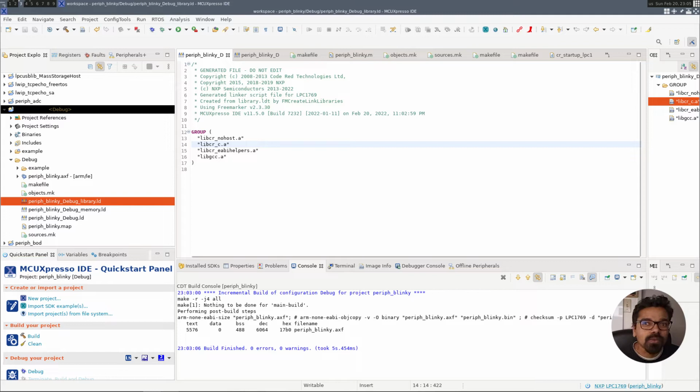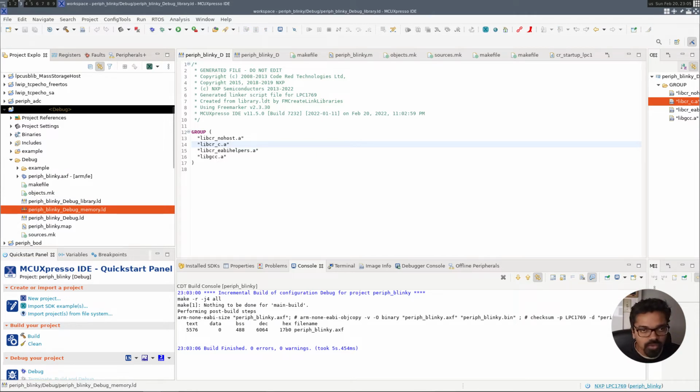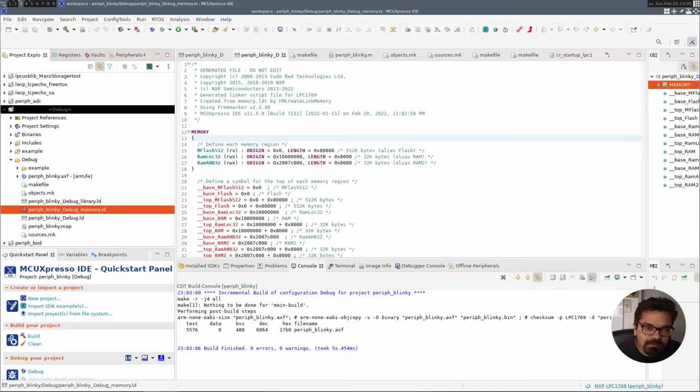But why is there an extra step over here? The reason we have this extra step, no matter what the chip is or who the manufacturer is, is because you need to compile your code based on a very specific target. That's number one. But two, that target might have a different memory layout, and different pin configurations. In this particular case, memory layout. Where do you want your code, and how do you want your code to be compiled? Where do you want to start your execution? Where's your heap going to start? How your memory flows. And that's really the instructions that this particular file is giving.